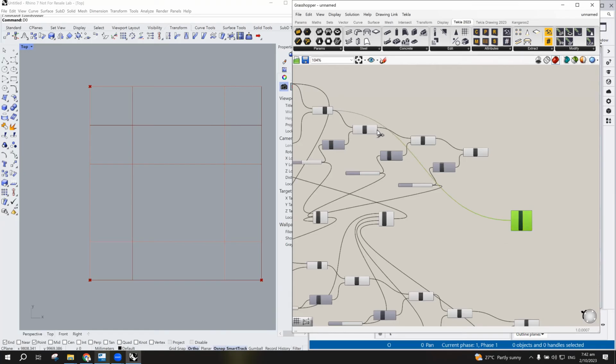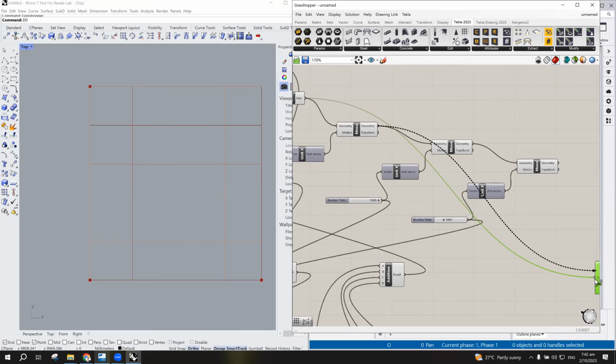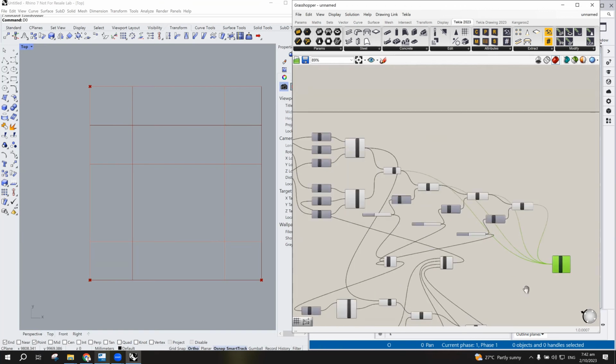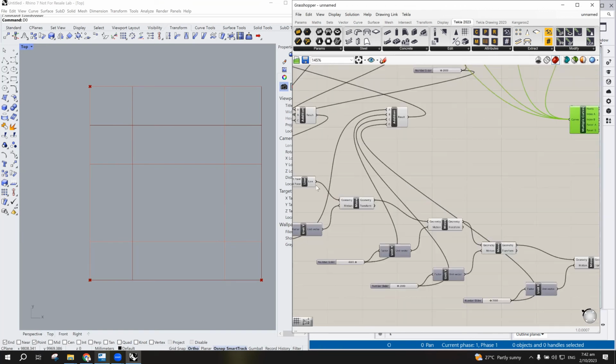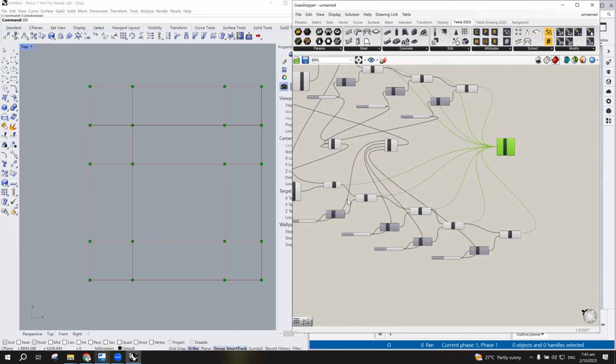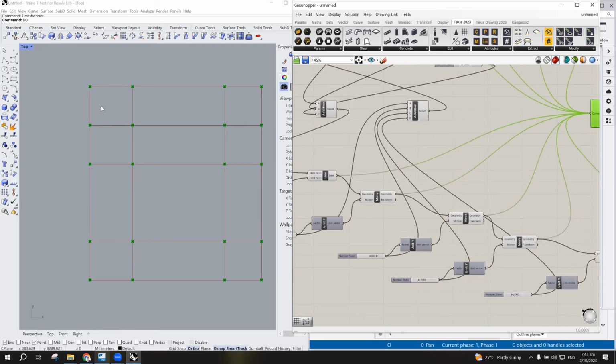One, and then here, two, three, four. And then you just connect all the lines here. This one, see the intersection. By the way, you need to press the shift key to add more lines. The shift key enables you to combine those lines. See? Now, the intersection of those lines creates the points.